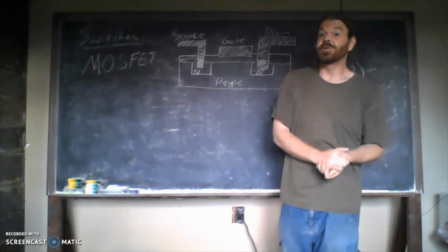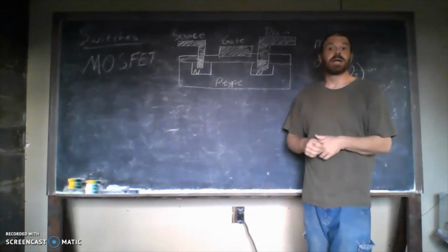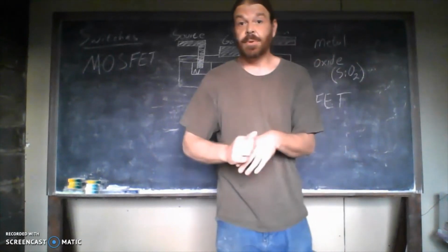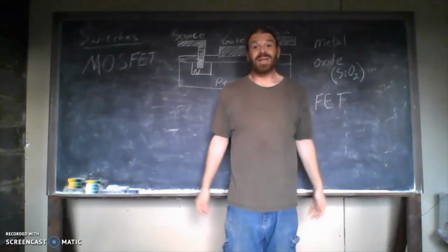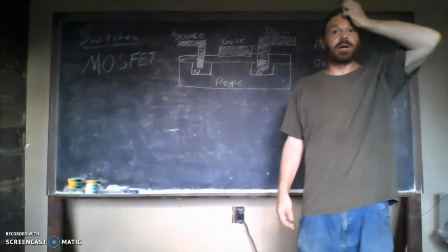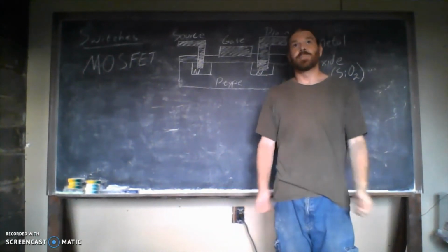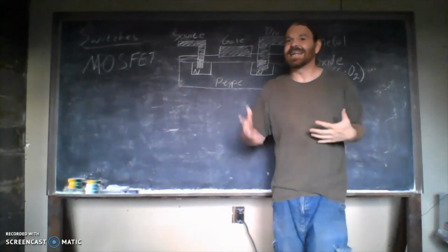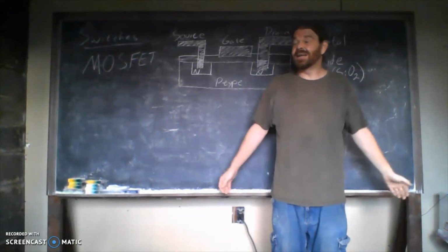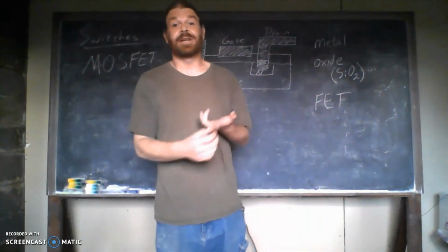Small things, right? Low voltages. But those aren't our only machines that need this. We might need that on big machines. So the transistor, like the one I used in the example earlier, can handle up to 6 volts between emitter and base. I think it maxes out, I'd have to check the data sheet, I'm pretty sure around 60 volts. So 60 volts is a little bit, but that's not going to run much in your house, right? Not going to run your coffee maker. Definitely not going to run your stove.